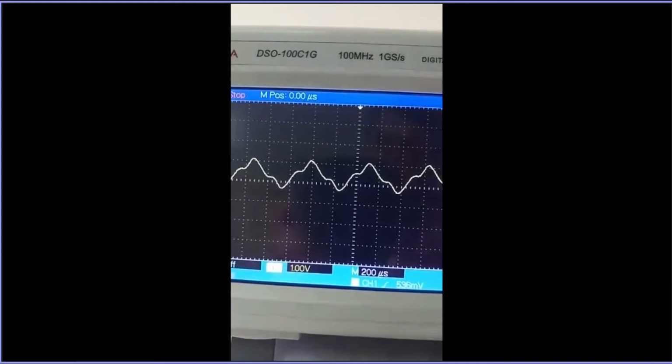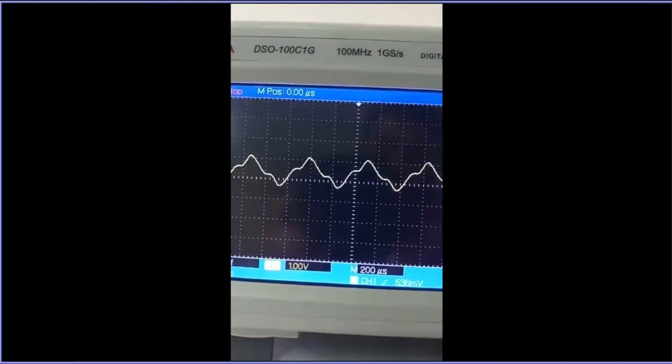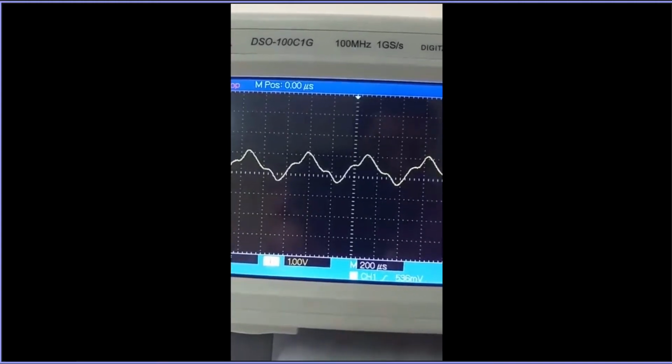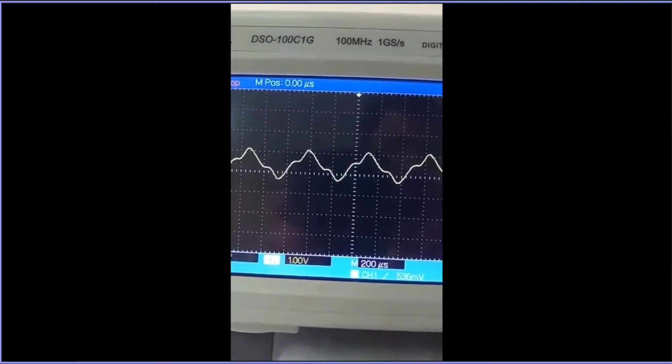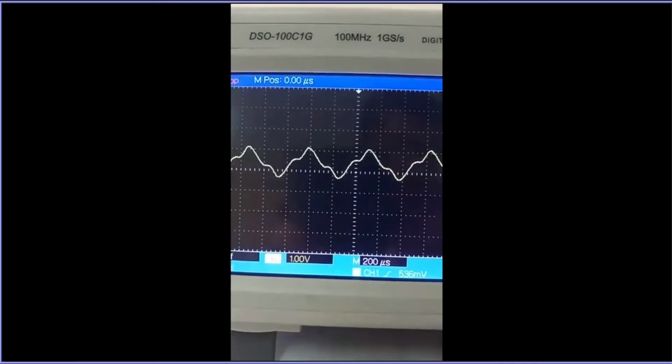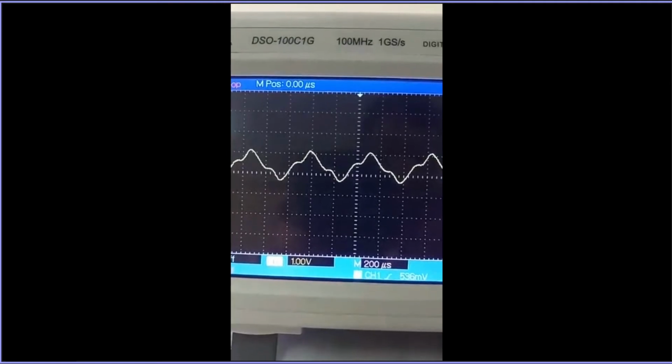And if we compare, we found that the best reconstructed signal comes from the sample and hold circuit, then flat top, and at last the worst is given by the natural sampling, right? Because this output is better than your flat top, the natural one.